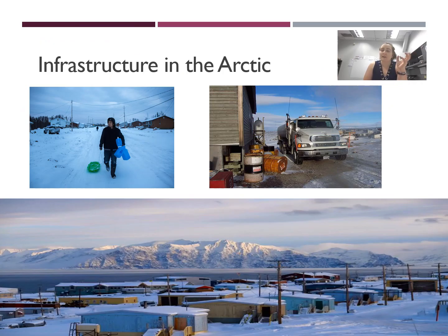Infrastructure in the Arctic: you cannot bury anything underground in the Arctic because of permafrost layers. And when the permafrost layers freeze and thaw in different seasons, it shifts soil around and can cause shearing of pipes. It can cause massive issues with foundations. And so what happens in drinking water and wastewater systems in the Canadian Arctic, and actually in Alaska as well, is we actually truck services.